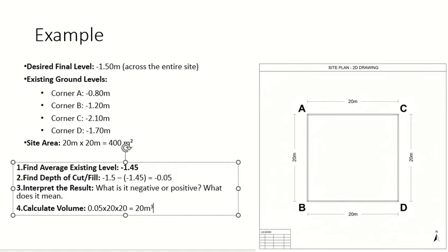There's another method in one of the books, which is called the grid method. You can find it online as well. Maybe you used it in surveying for area calculation, or in contouring. In the grid method, they will give you more elevations. Instead of a block of 4 points, you will make a grid, and at each intersection point you will have an elevation, so you have more values to calculate the average.